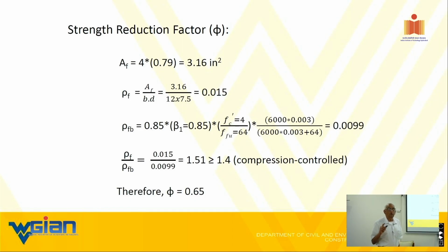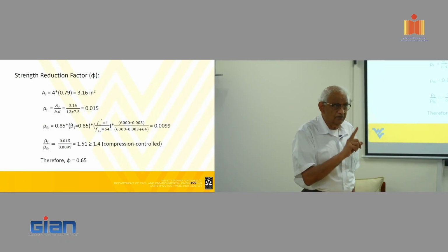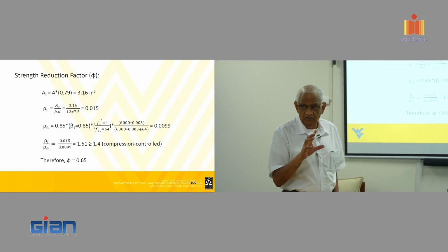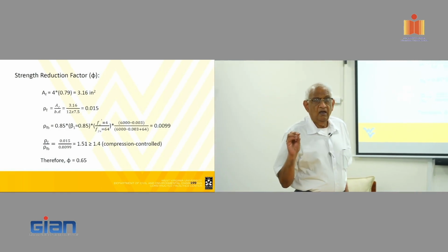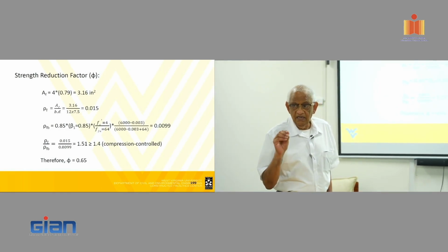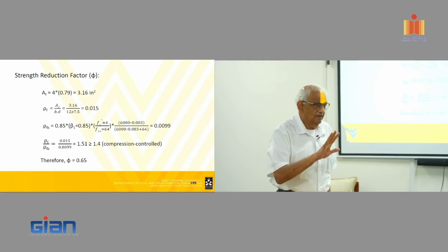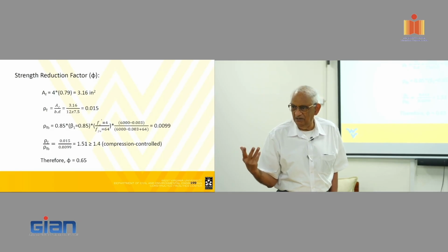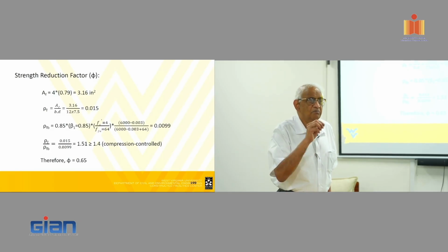Anyway, before we go there, what we typically do as a starting point in the design of a bending member with steel reinforcement is you start with approximately 1% for beam bending as the amount of steel, 1% of the cross-sectional area b times d. d is the effective value. That's just a guide, remember. It could be 1.25%, it could be 0.8%, but that's for beam bending.